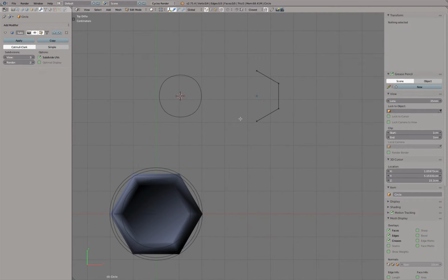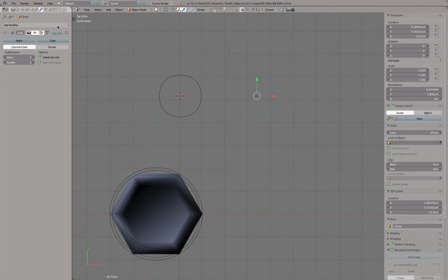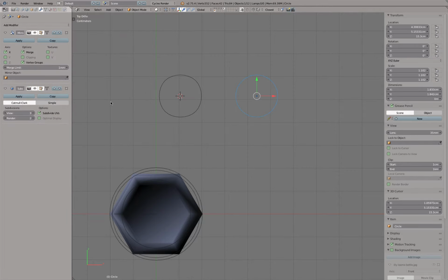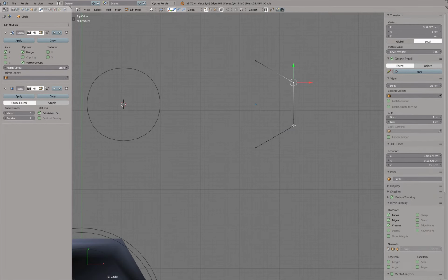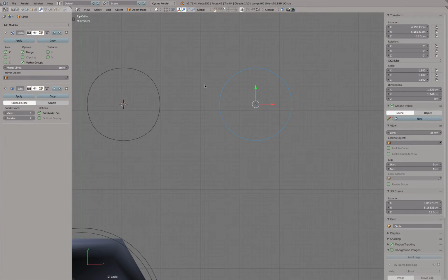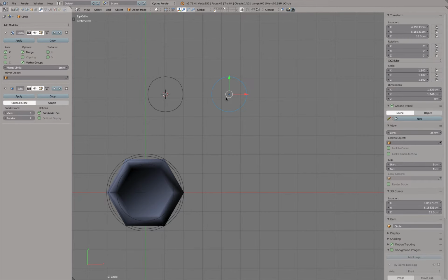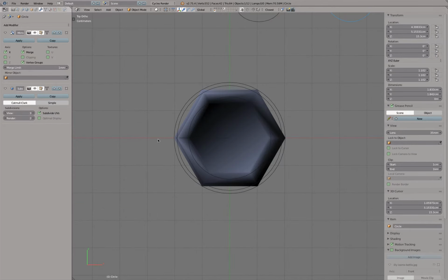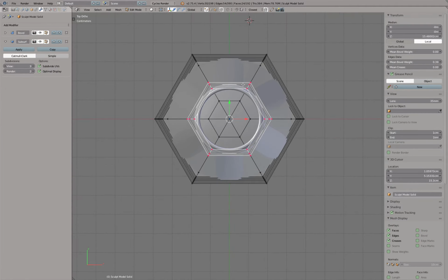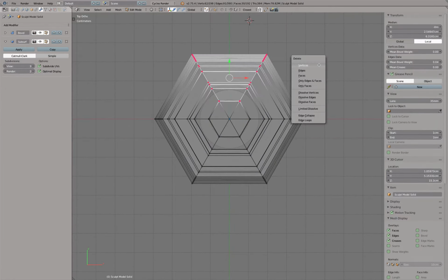The other advantage actually of 6 points is simply this. I could delete these 2 points. Now I have an arc. I could add actually a mirror modifier, add this mirror modifier on top of the subsurface, and I have a ring again. But I actually only work on half a model. And that's simply because with 6 points you have along the mirror plane 2 vertices. So in case I would slice this model apart, maybe let's go to here. Let's select all this and delete it.